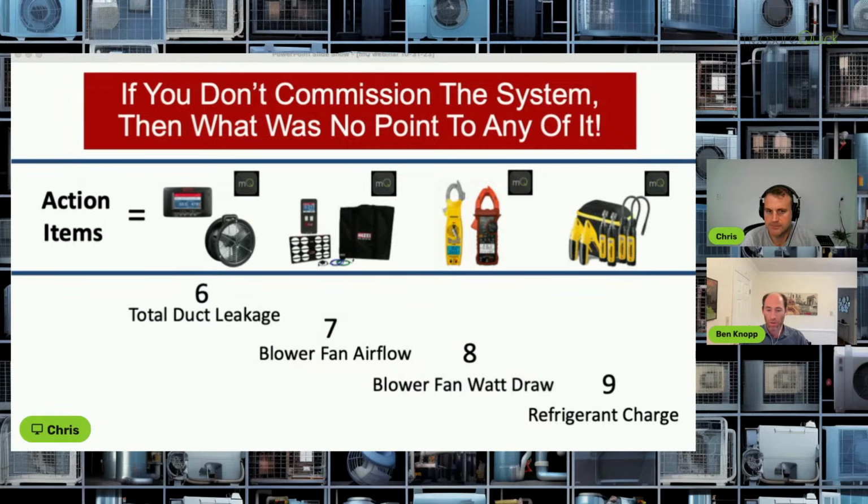For this home, that was 4.5 gallons of water a day that get evaporated into the air and need to be removed by the cooling system and/or dehumidifier. Okay, so 4.5 gallons. Air infiltration for this house, 5.8 gallons of water coming in from air leakage. Now this is during peak dew point conditions. So this is when it's super humid outside. So any air that comes in brings in a lot of water with it.